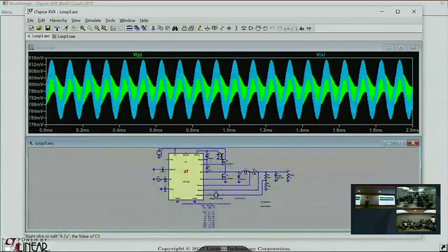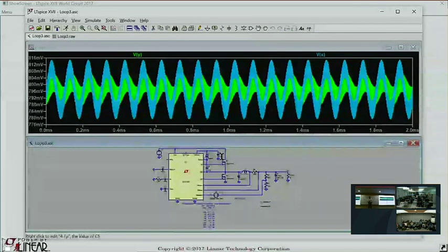Of course, if you drive a signal, the transfer function changes very radically, and you will probably at some point in your life find a power amplifier that's stable at equilibrium, but if the output gets close to one rail or the other, the transfer function changes so much it starts oscillating. You'll probably see one like that in your life at some point.